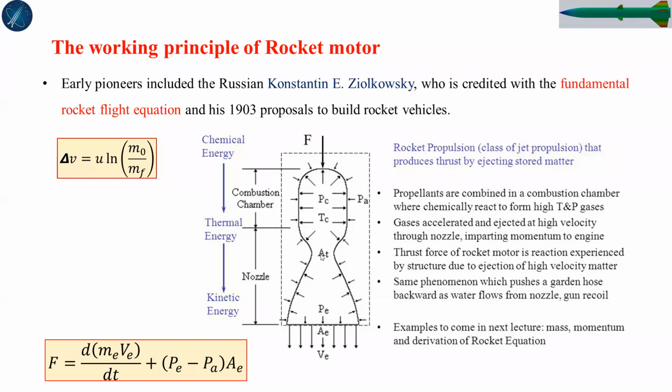After Mach 1 to the exit region, it is the supersonic region. So it is divided into 3 different regions, and the principle of momentum conservation works here, the principle of mass conservation works here, and the principle of energy conservation works here.